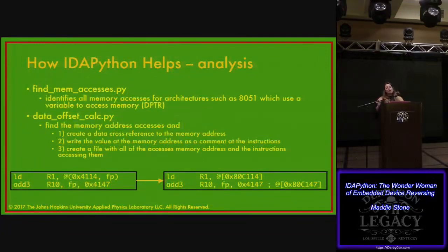So moving on to analysis. We've got our database, it's all triage, we know this is code, we know this is data, this is strings, this is RAM, this is where SFRs live, what now? So one of the key points that I always felt like I was spending so much time banging my head against my computer was understanding how these functions were interacting, reading, writing memory.